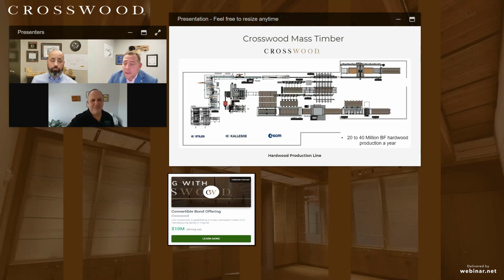Yeah, the only thing I'll add to that, and I believe Kurt might have touched on it a little bit, is with these mass timber buildings, grid spacing really comes into play. And when we talk grid spacing, we're talking about columns, right? So mass timber, these tall buildings, I'm not talking residential buildings, but up to 18 stories, is columns. The spacing between those columns is typically 25 and 30 feet. A 40-foot panel is going to easily span that 30-foot column to have that open space look that you get with these mass timber buildings.